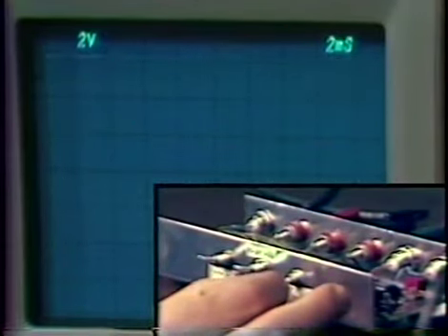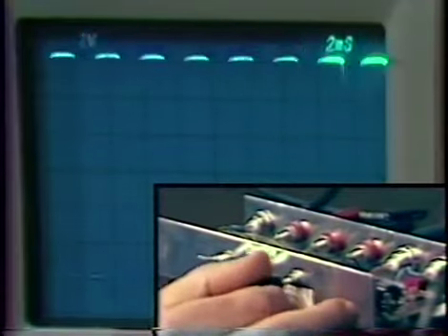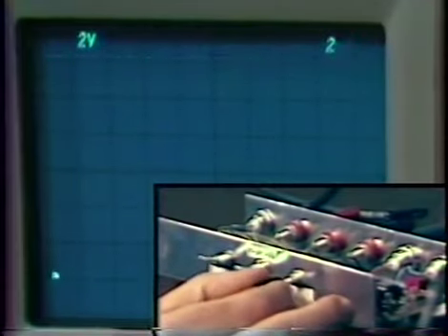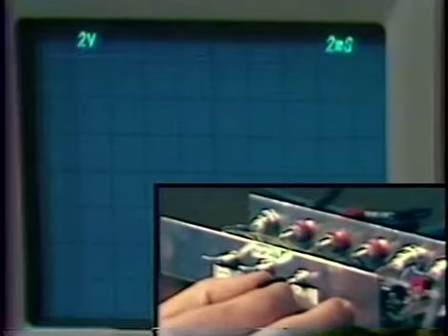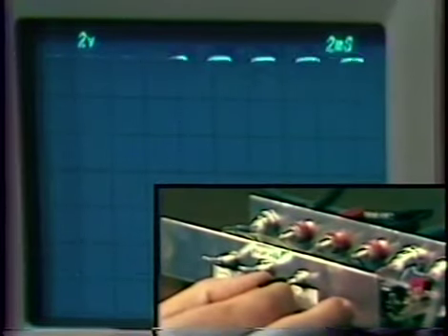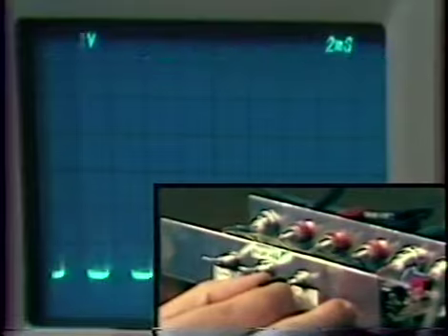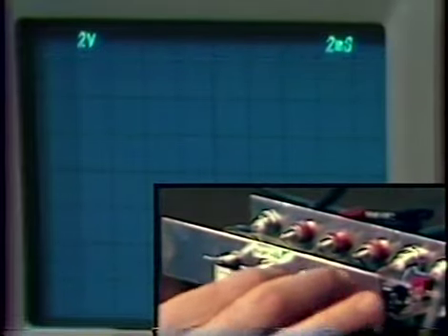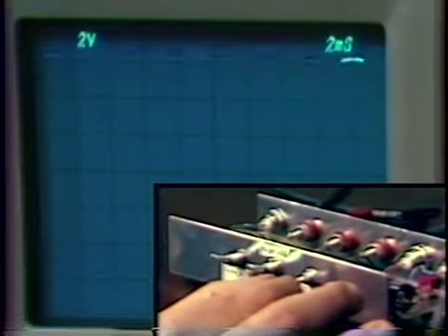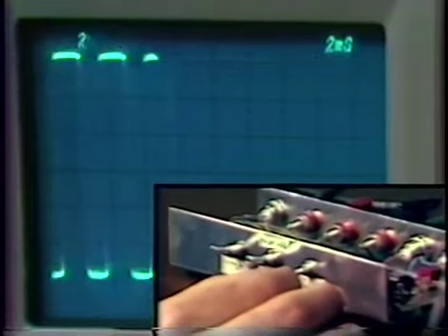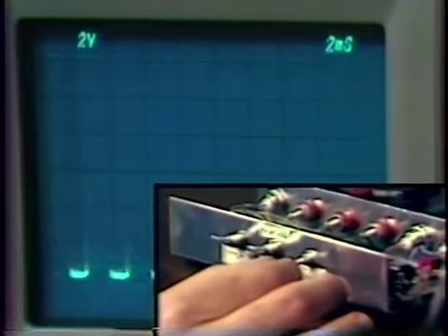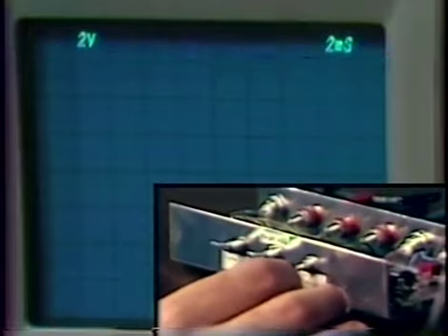All of a sudden, we break into oscillation. And if I try to set A naught equal to 80, I can't do it because we have large enough signals in the system such that the system saturates. And in spite of my attempts to increase the A naught F naught product, the system thwarts me. We're now into the limiting region of the nonlinearity. There's nothing I can do about it this way. Well, how do we get out of this?